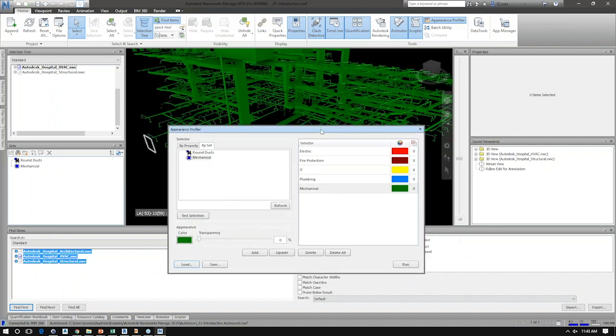I'll reemphasize the purpose of this is as you're working inside of Navisworks and you're manipulating the geometry on several different projects, you don't want to have to do this every single time. Incidentally, you can save all these sets and export them out to an XML file, right? So if you build queries within Navisworks that you want to reutilize on every project that you work on, you can do so.